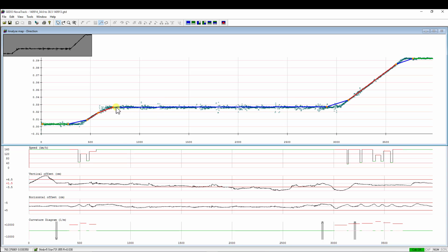If it suddenly changes color, just press A again at the beginning of the straight element, and it will be averaged to all the measured points. All right, so we have finished. It's important that you take a closer look that straight elements do not have any split points in the middle or anywhere along, because that might run into an unsolvable solution.